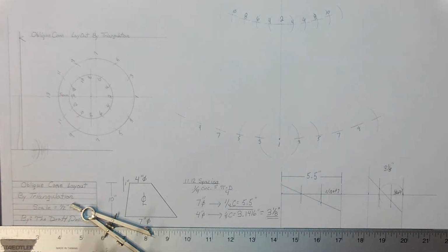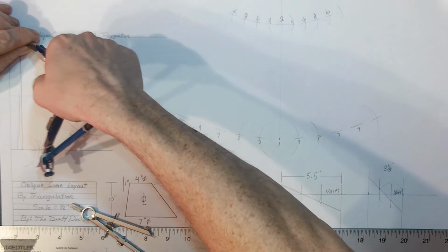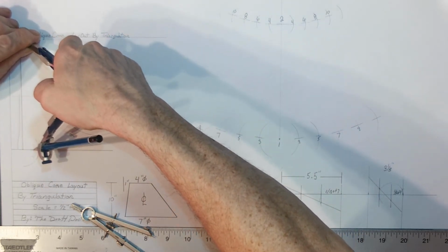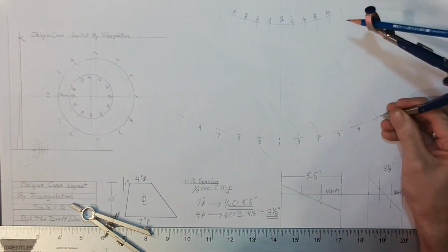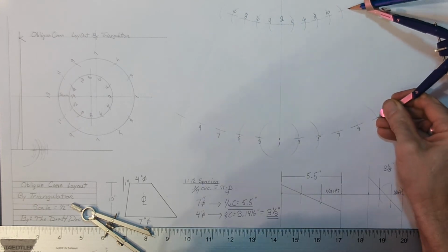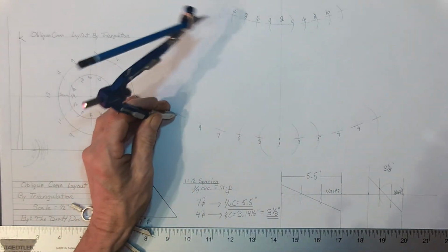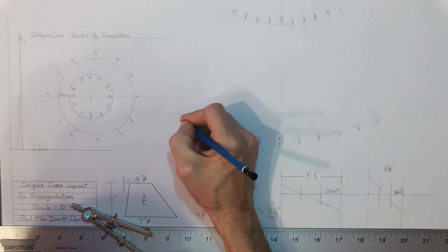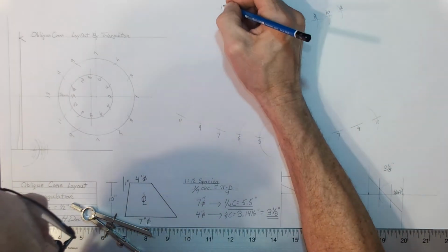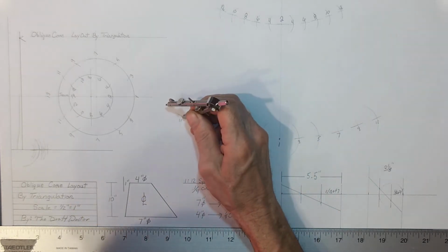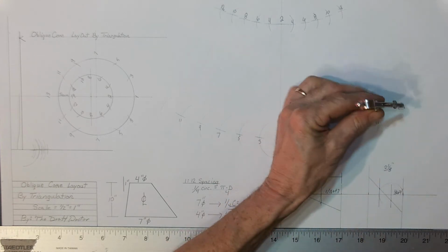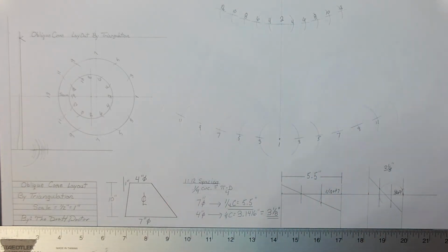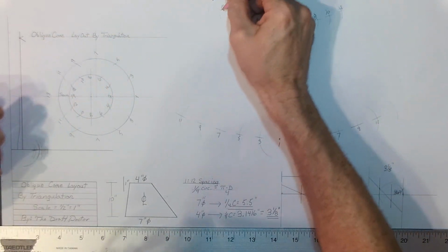And next is from 11 to 12. There's my plan length of 11 to 12. Here it is plotted on my true length triangle. And now the true length of 11 to 12 right there. And from 11 to 12. 11, 12. Back to my 1/12 spacing. Somewhere on these arcs, we'll find point 13, I'm sorry. And somewhere on this line or arc, I will find 14.